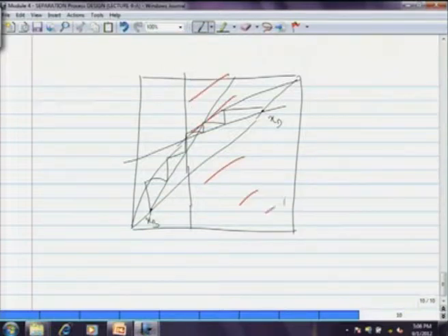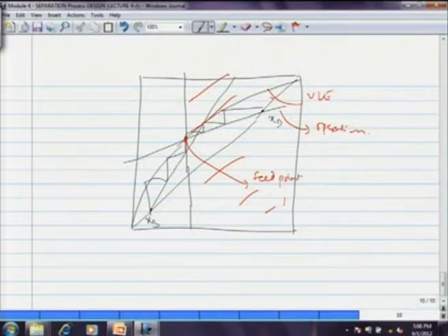Okay. We have considered only this portion, because we considered the cross section or the point of intersection of the VLE curve and the operating line as our last point, as our origin. So, we have determined the number of plates in the upper section of the column. This point is essentially the feed point. Okay. So, we have determined the number of plates in the rectification section.